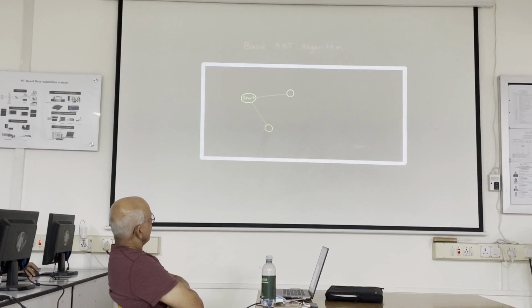So we already have two paths in our tree, and both are venturing out into different parts of the state space. A new random node, and again we connect it to the nearest, which is growing one path even further into the open space. This is why the algorithm is called rapidly exploring random trees. When there are large unexplored areas, like we have, then there's going to be a good chance that a random node is selected in that area. And this has the effect of adding new nodes in places that cause the paths to venture into unexplored areas quickly at the beginning, hence rapidly exploring.